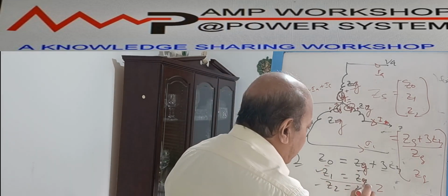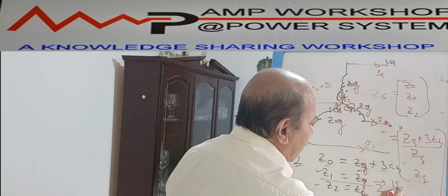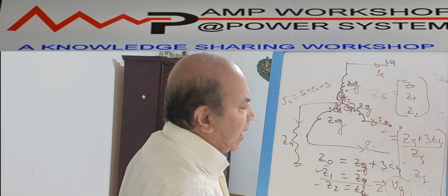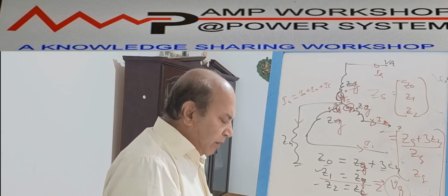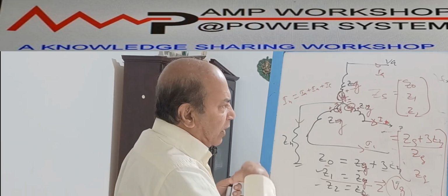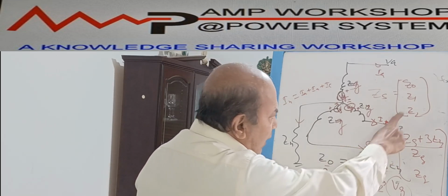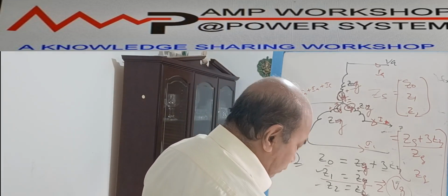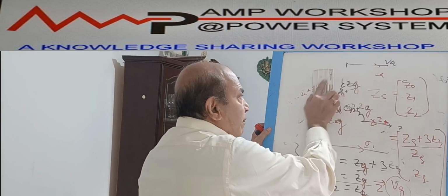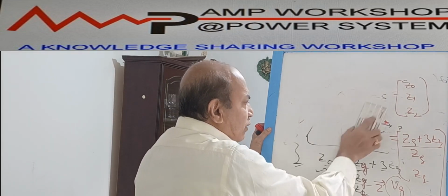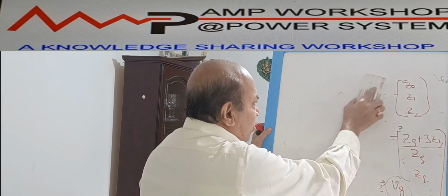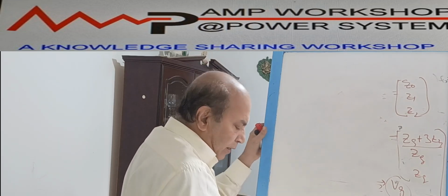And in the positive sequence network there will be a presence of a voltage source. So this calculation will be the same as we did for the rotating equipment. So I am not going to calculate that again. That will be the sequence impedance for the rotating equipment. So what is the relation between sequence impedance, sequence current and the sequence voltage for the generator? We can develop it very easily.